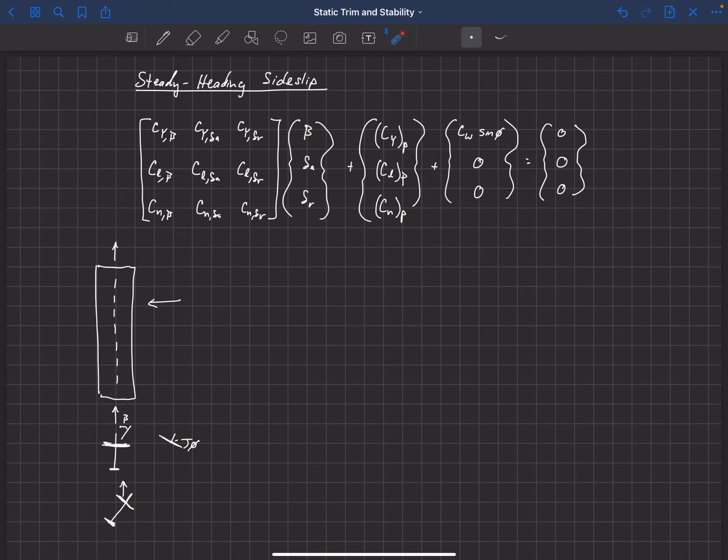Theoretically, you can get to a zero bank angle. Now, this is challenging to land because when we touch down on the runway, our landing gear is not aligned with the direction of the runway. So what you'll see quite often is that the aircraft will come in on approach crabbed into the wind, and just before they touch down, they'll kick the rudder over, which swings the nose of the aircraft to be aligned with the runway just as they touch down.